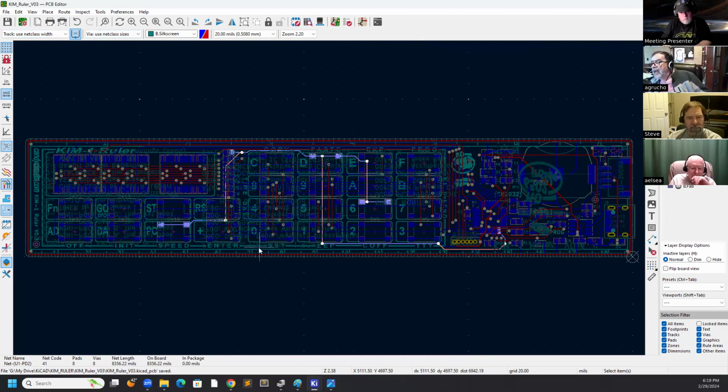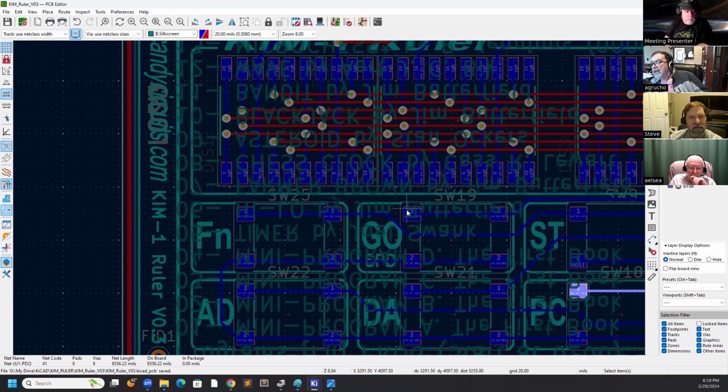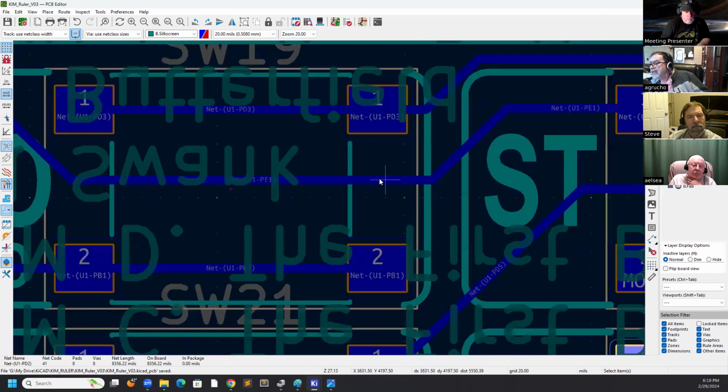It's got to be at least 3 layers. What? It's got to be at least 3 layers. You've got a ground plane layer. No, but my ground plane is in the same layer as the lines, you know. It automatically goes everywhere trying to cover all the empty spaces. And you have rules for the distance between your connections and the plane.